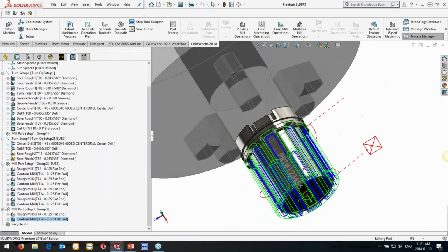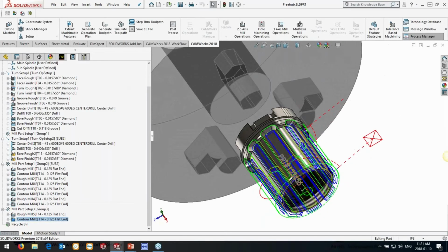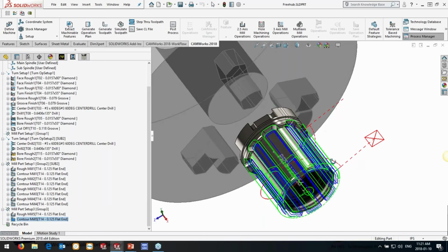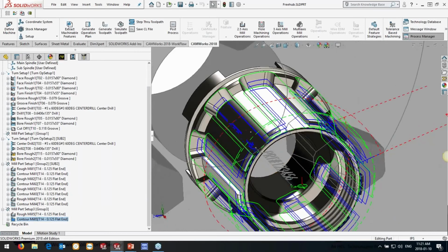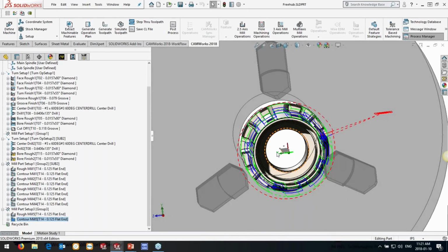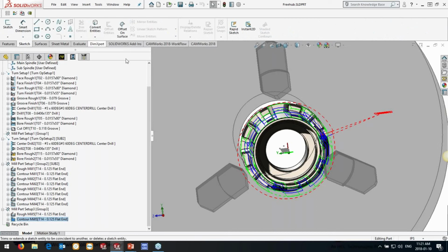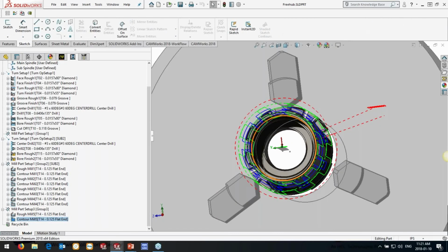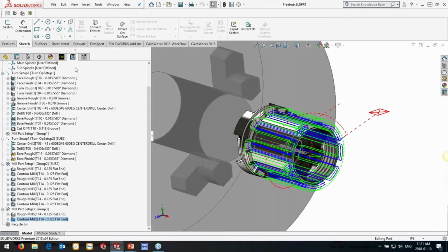If we're doing things like engraving, so if you want to use a fourth axis or you want to engrave with the mill turn, basically the text that you're engraving with usually needs to be at the actual main axis here. So you put in a text as a sketch using just the regular sketch text option. Put it on a plane through the axis of the part. Doesn't really matter which orientation, but it has to be on the plane through the middle.